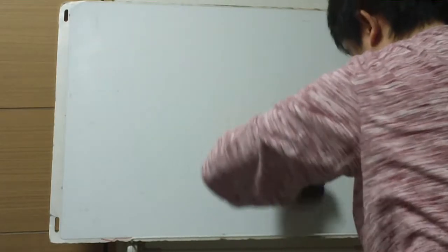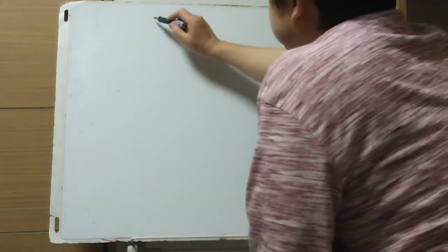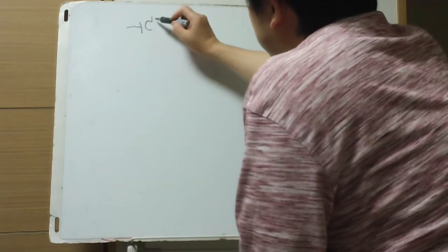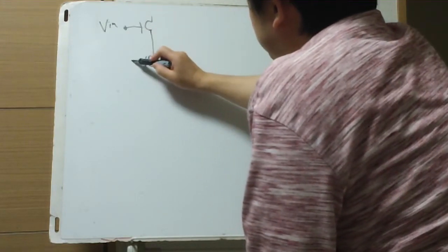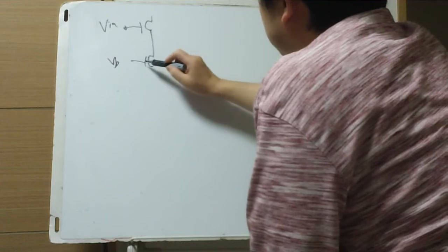Next, the source follower, using output voltage gain. For the source follower, input referred voltage noise is considered, and input referred current noise also, like the common source amp. For the source follower, this is Vin and this is Vbias. This is a constant current bias.